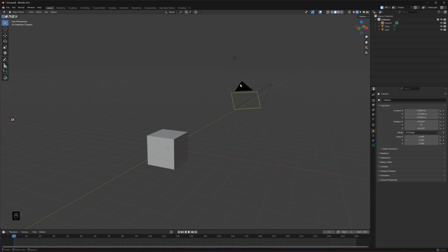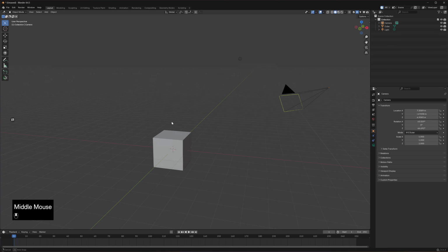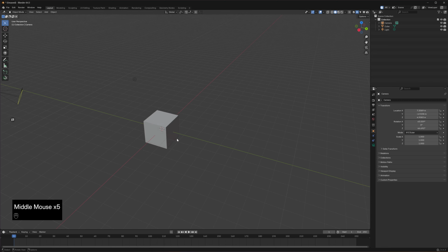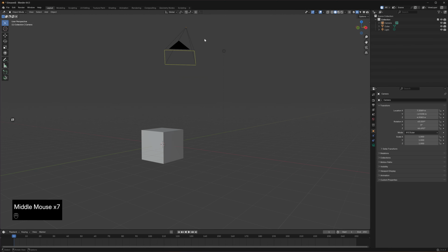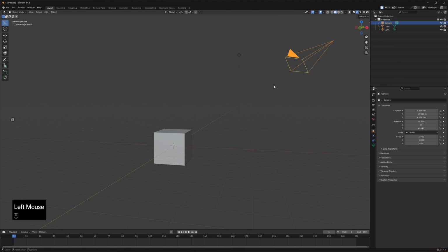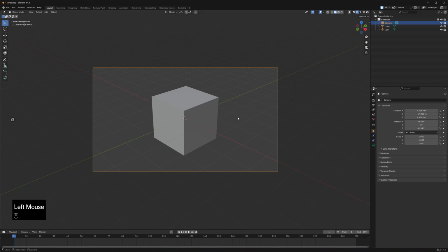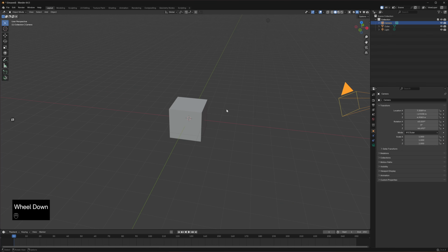Unlike Photoshop or 2D projects, in 3D, we have to tell Blender, okay, I know that I'm looking through my viewport right here, this is what I'm looking at, but I want to move around freely and I don't want to constantly go back to a specific point to create a render. So to solve that, we have a camera which we can place anywhere we want, and that view is going to be locked to what we're seeing right now. And we can move and position anything that we want and just make sure that eventually all that we need to do is render our camera view.